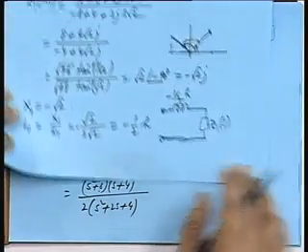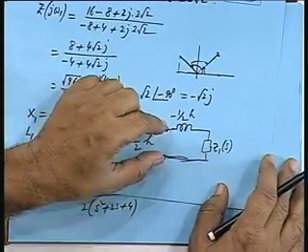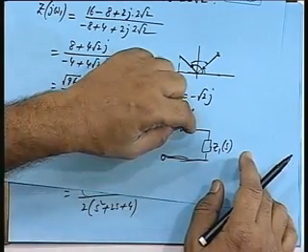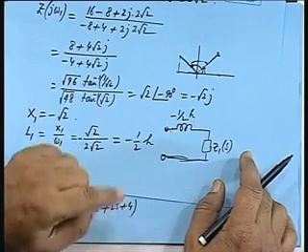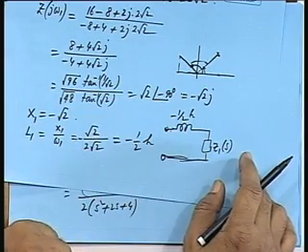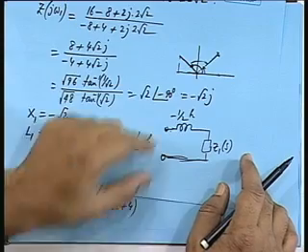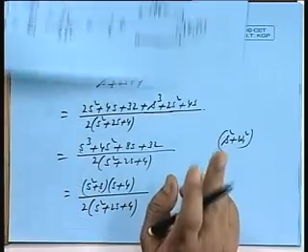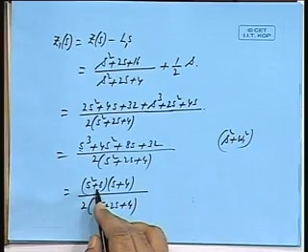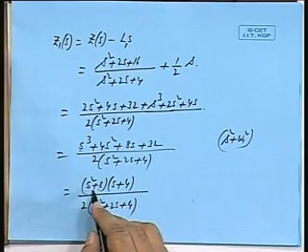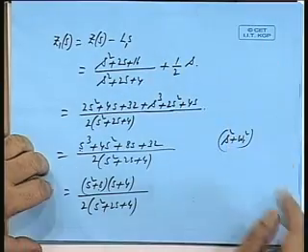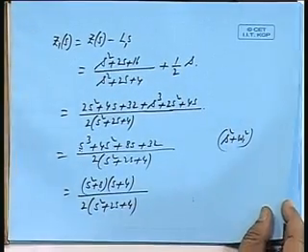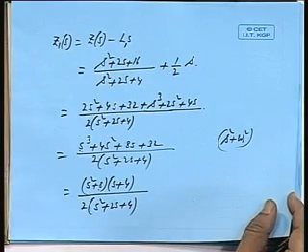Because what we try to ensure is this impedance at that frequency is equal to the reactance at that frequency of this coil. So, what will be the impedance of this? It has to be 0, because this impedance is equal to this impedance. So, this has to be 0. So, Z1s must have a 0 at that frequency. So, s square plus 8 must be a numerator factor of Zs, this Z1s. Otherwise, we could have a different factor also, obviously, we are making it equal to that inductor.